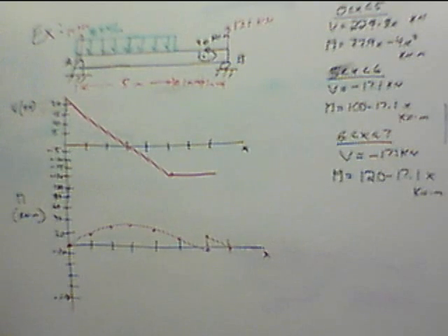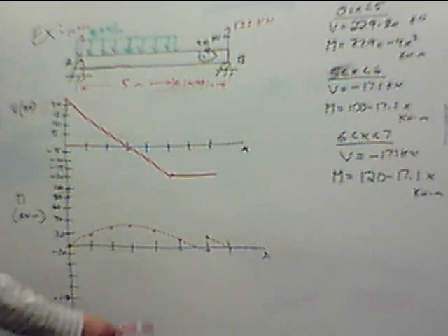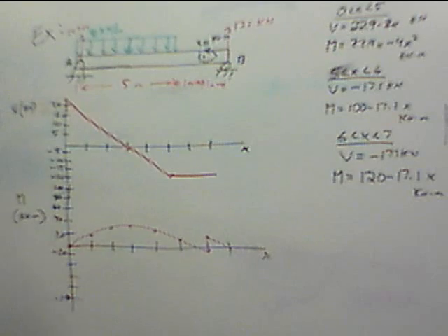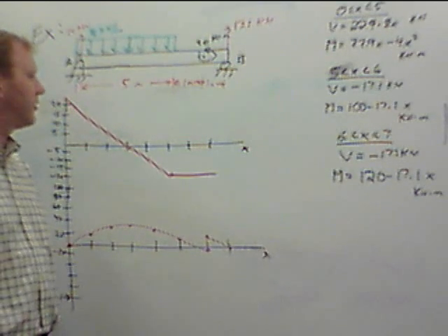So again, it's a good idea at the end to sanity check these things. Make sure you've got discontinuities at the applied loads. Make sure you're starting and ending at the values you should expect to. So that wraps up shear and moment diagram.